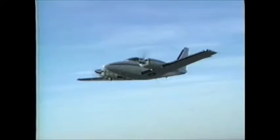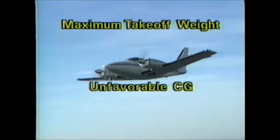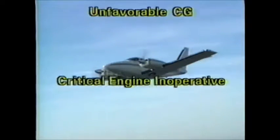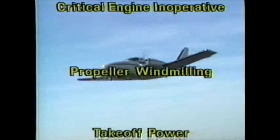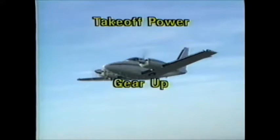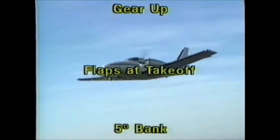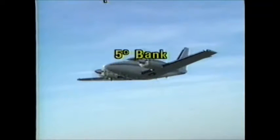This normally includes the aircraft loaded to maximum takeoff weight, the center of gravity in the most unfavorable position, the critical engine inoperative, the propeller windmilling, the operating engine producing takeoff power, the gear retracted, the flaps in the takeoff position, and up to 5 degrees of bank established toward the good engine.